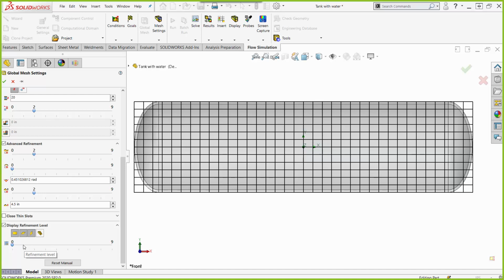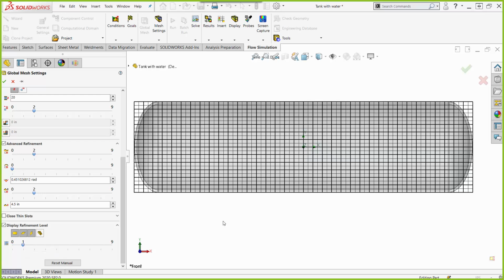And for a tank like this, that sloshing could really be anywhere, so I'm talking about refining everything in that tank. This level 1 refinement, this is what I used for my comparison studies. It is still a little bit large, but it is fine-tuned enough to get me detailed answers and to converge on results and to quickly get me answers, more importantly, within an overnight solve scenario so that I can compare those within a day, right?